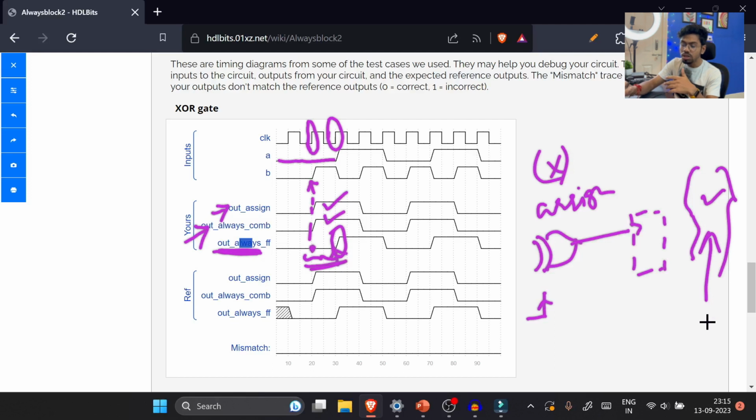While you are doing the XOR calculation, they are maybe busy doing something else. If you give an output in between, probably we'll get a wrong result, right? You are changing their input signal in between the clock. There are many concepts like setup time and hold time, and we are violating those for sure.